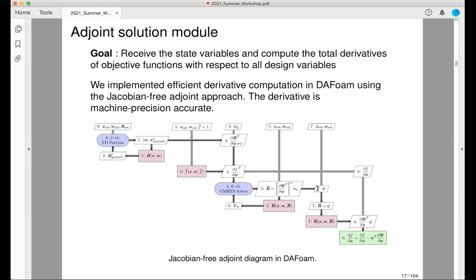So let's assume that our X is just one control point. We only have one design variable, okay? Then what we do is that we first solve the flow, converge your steady state CFD, and then we have a converged residual. They should be very close to 0. Then we perturb this X. For example, the initial coordinate displacement X is just 0. Then you converge the CFD, you get very close to 0 residuals. All the residuals are 0.